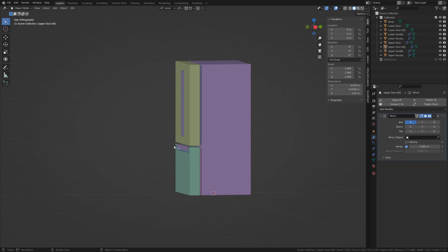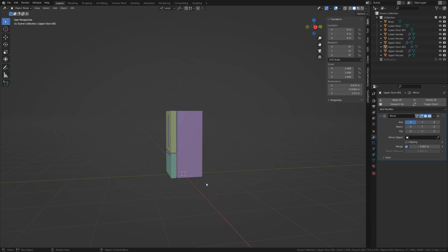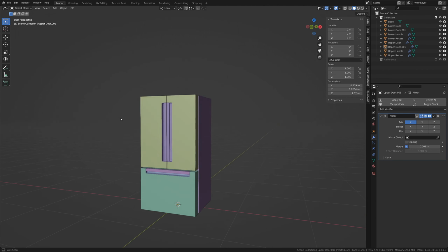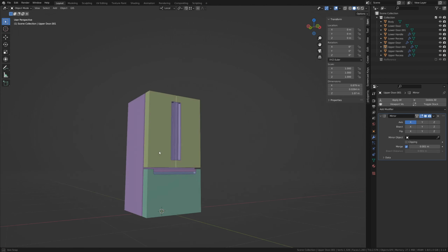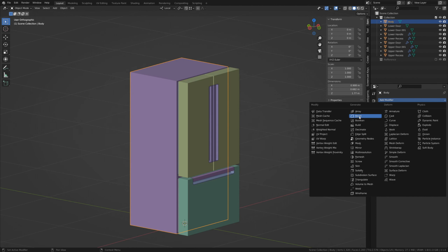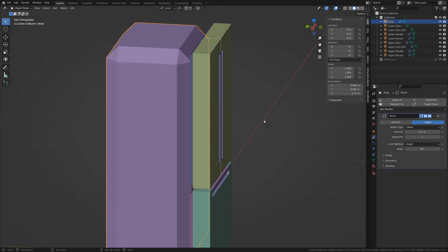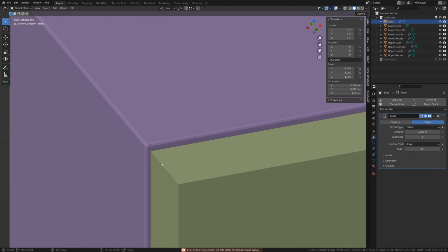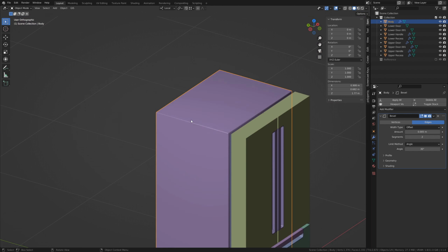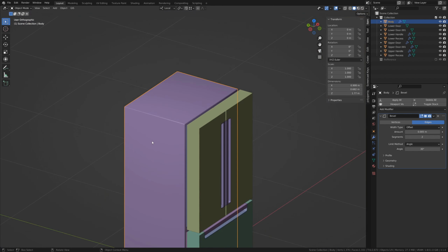Now all of our objects are in place. You can take a look around, go into perspective mode. If anything looks off, or if you notice any bad geometry, fix that now. We're going to start adding our bevel and subdivision surface modifier. So first let's add a bevel modifier, and you'll see what it does. And the bevel parameters are set here. Let's set it to 2 and bring this down to 0.005, I think is what worked for me. We don't want it to be too sharp. And at this point we can actually right click and hit shade smooth and select all objects and do that.